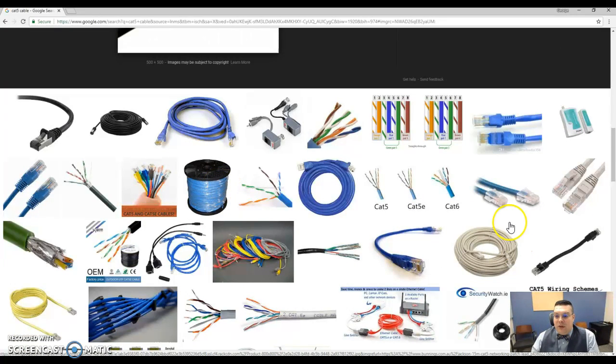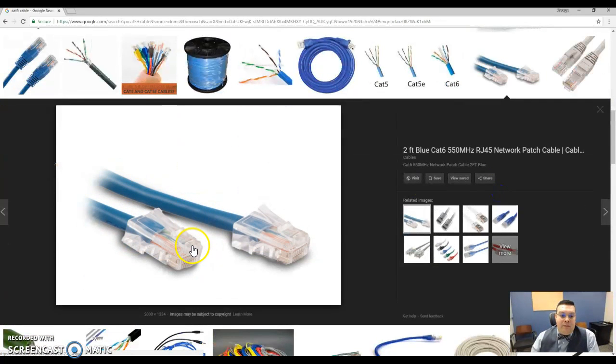Let's see if I can get one. When you do terminate, you're going to have your little RJ45, and notice that there's a pinch point that crimps onto the cladding. See how this is pinched on the blue? That whole cable termination is now being pinched at that point, so we can say the weight of the cable is supported by this pinch point here, not with your wires back here.